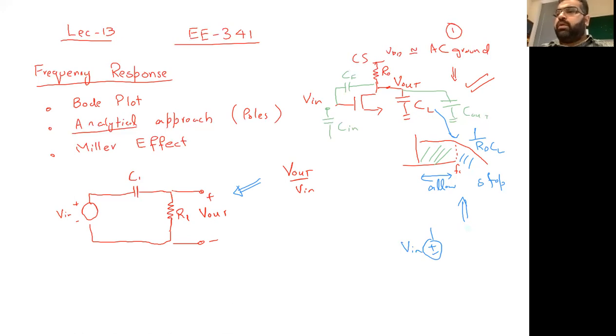Sorry. So V in, if I have a resistor here, and then I have a capacitor here. Okay, and I'm taking V out. So whenever I take the output on the capacitor, the voltage starts reducing based on the capacitance value at a higher frequency, because the capacitor starts playing its role. It's ultimately a voltage division.